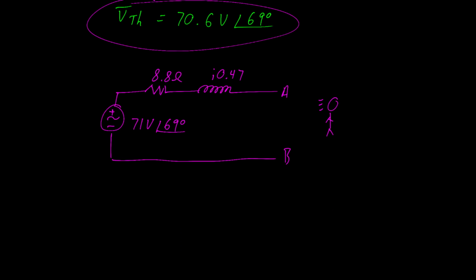One final step, let's calculate the actual value for that inductor. Here we use the reactance formula in reverse to solve for L. And it turns out that L is about 1.2 millihenries.